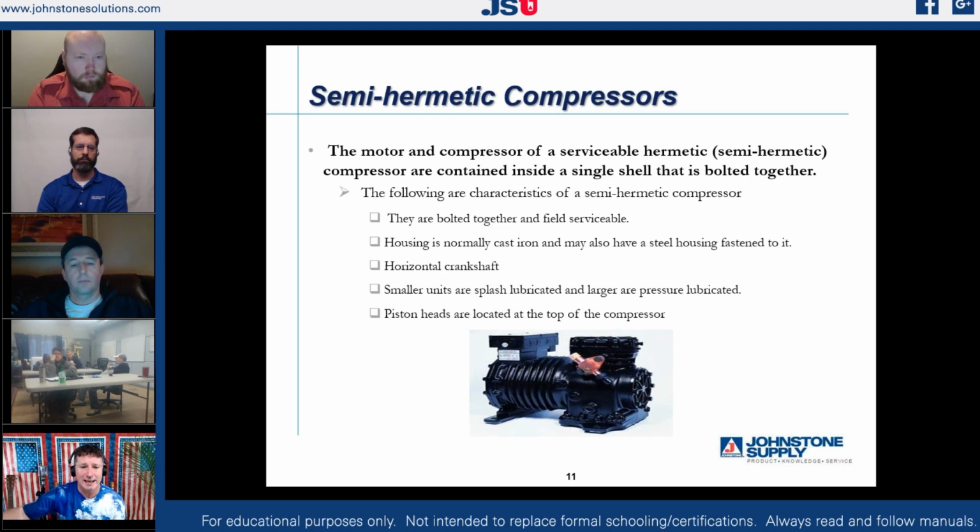In the field that I came from, I was rebuilding these routinely. When I was doing maintenance on my refrigeration racks, I was looking at compression ratios on my individual compressors to see if one wasn't pumping properly. And then if it wasn't pumping properly, I would verify that by doing a pump down process.